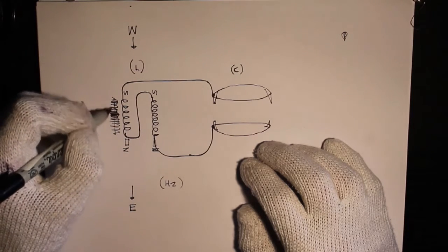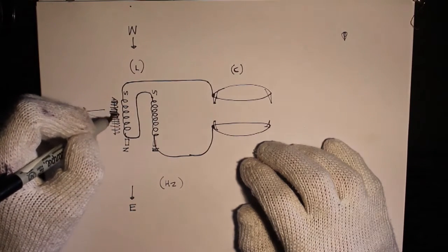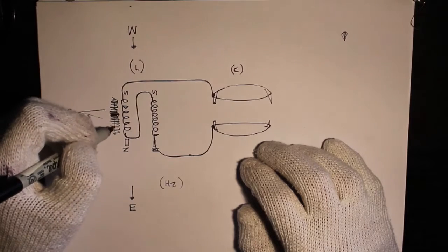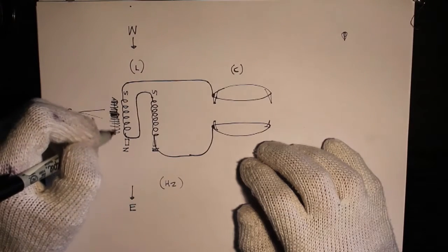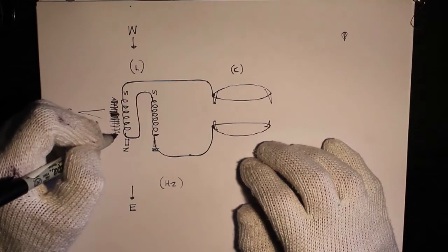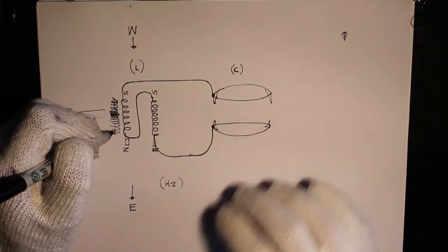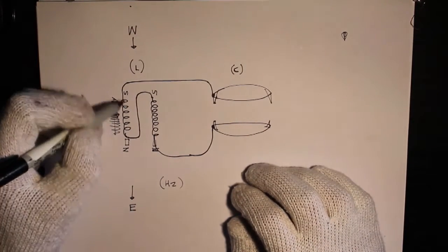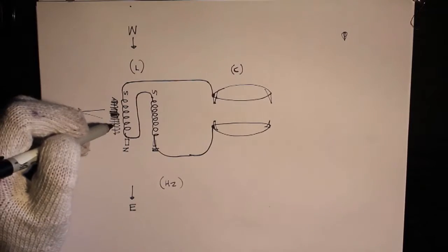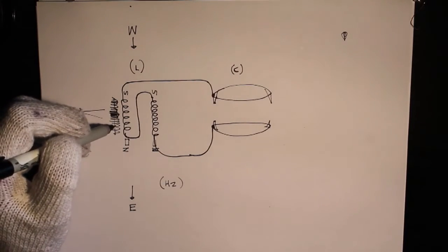The wire is insulated, just by varnish. It's insulated for electrical purposes only, not energetically. Energetically, it's better if they're not insulated, but they have to be, because they might contact the magnet or any part of the circuit, and short circuit.